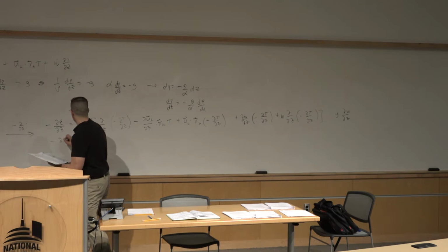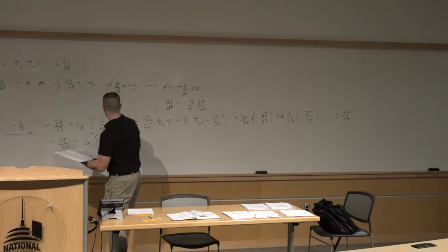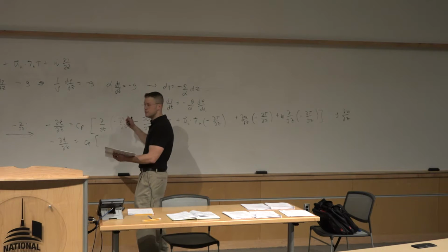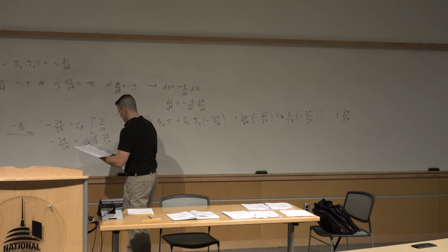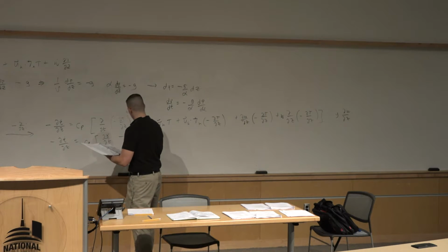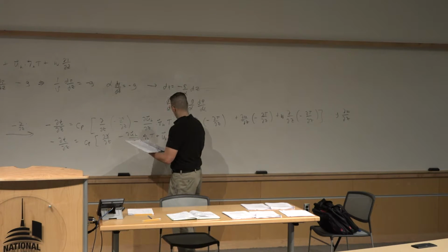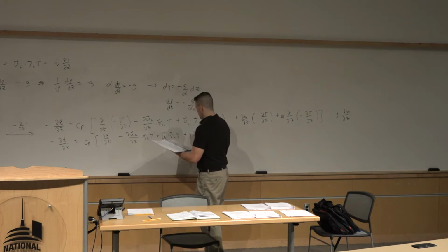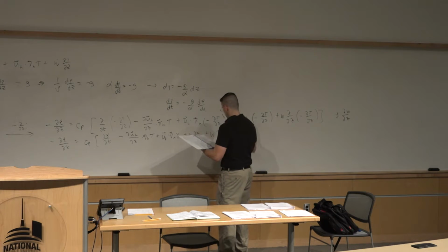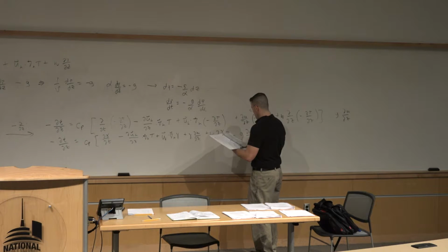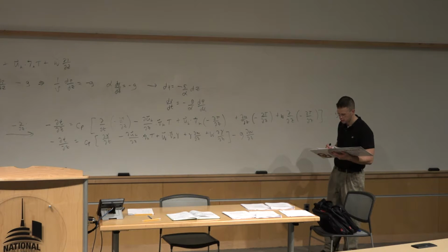We have minus partial Q dot, partial Z. And that's going to be equal to Cp times, well, we have partial T of gamma. We have a gamma here, so that worked out relatively well. Partial gamma, partial T, minus partial UH, partial Z, dot del HT, plus UH dot del H gamma, plus gamma partial W, partial Z, plus W partial gamma, partial Z, minus g partial W, partial Z. So we've effectively just placed gamma in place of each of the minus partial T, partial Z's.